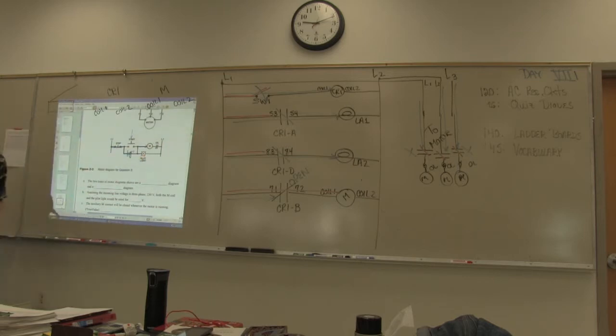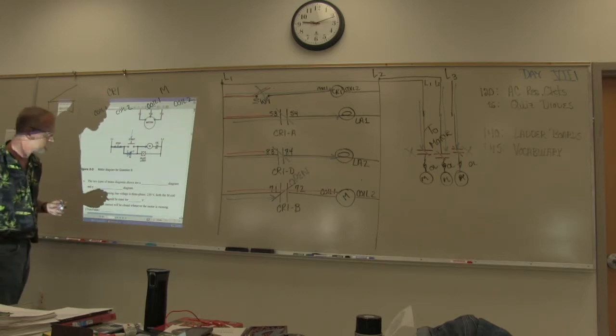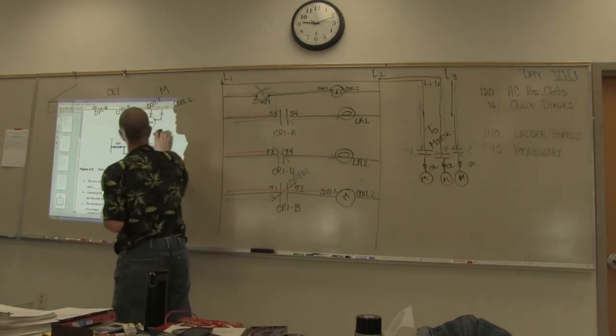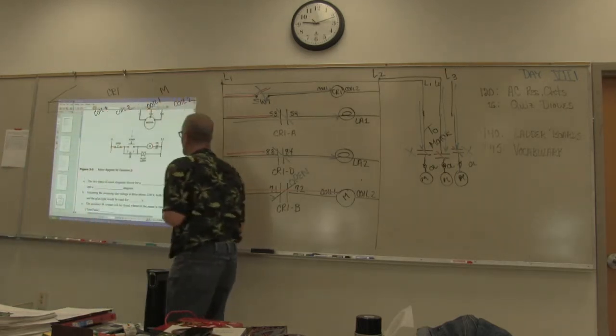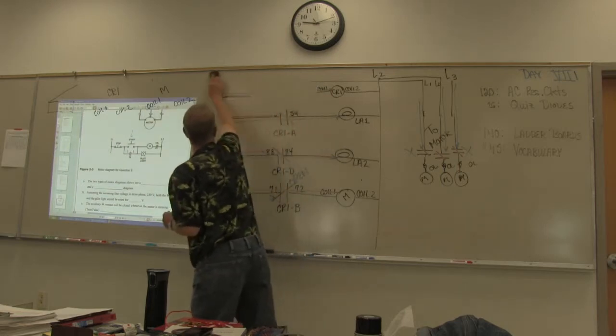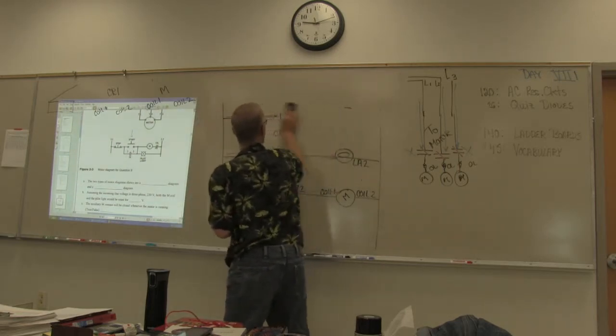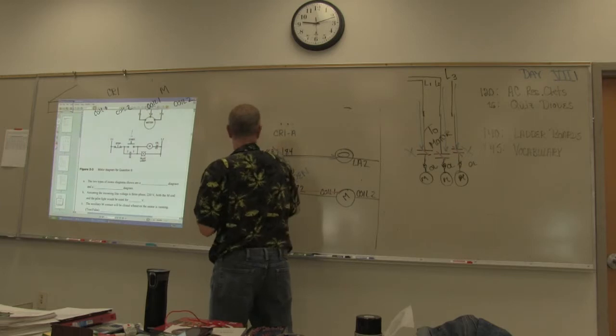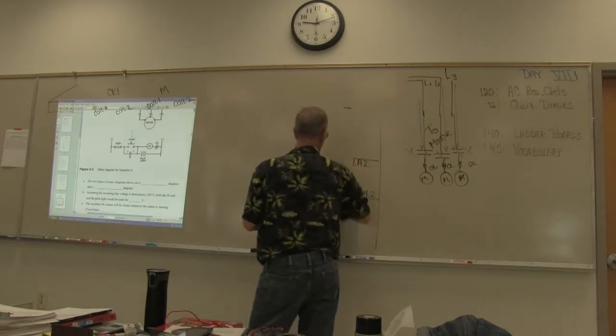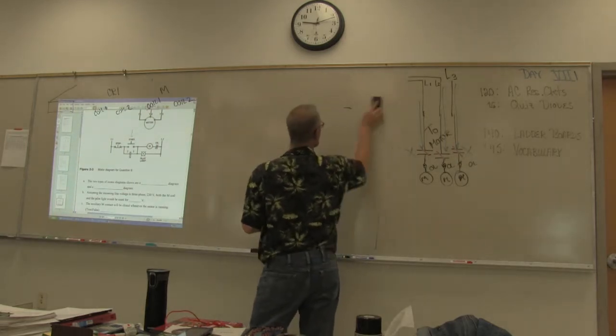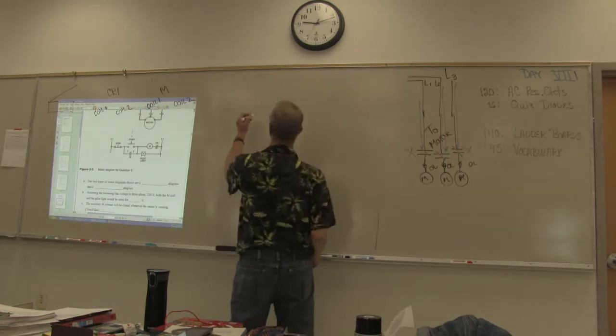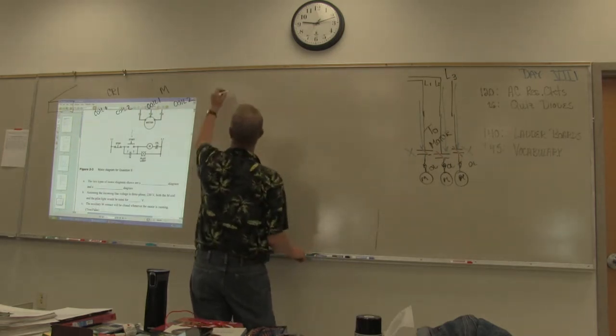So is the contactor wired directly to the start button? The way it's drawn, to me, it's not wired into the start button, so the power gets there. And I guess I'm just not getting why it's activated when the start button goes down. Well, you remember how a relay works? How if a relay is energized and anything is open, it'll reverse the contacts for that particular relay. So that M is a relay, but it's not energized because the start switch hasn't completed the circuit yet. So now it's an open circuit.